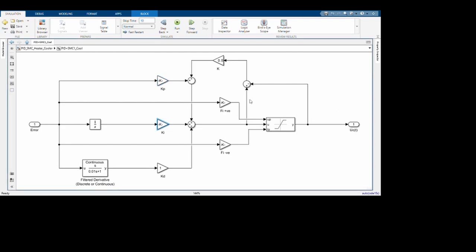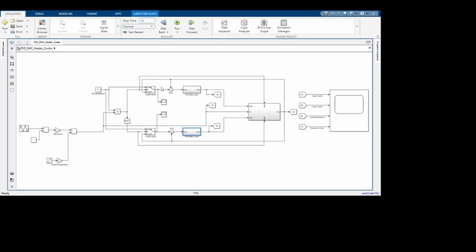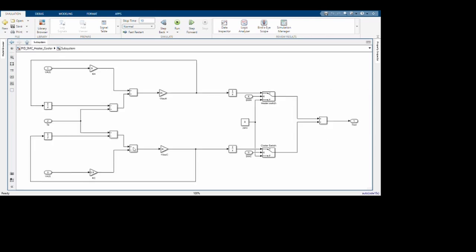Now you might be noticing that that is a much lower gain. The reason is because in this equation, yes, this is our plant equation. The upper equation is our heating equation. The lower equation is our cooling equation. They both use the same ambient temperature, which I described before, and they both have two algebraic loops where the output is basically a derivative of temperature, and one of the terms is the output temperature. So you have to integrate that output temperature in order to actually get the correct output. So there are two algebraic loops here.